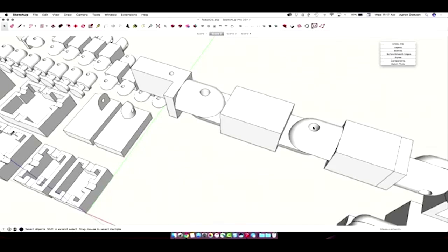And what I found is, again, because of the variance in the material, it's really hard to get a perfect, specific screw hole. So what I ended up doing was modeling it small and then just drilling it out. It's a little extra step, but it gives you a nice clean hole that you can put a screw through. So these are intentionally modeled smaller than the actual screws I used.